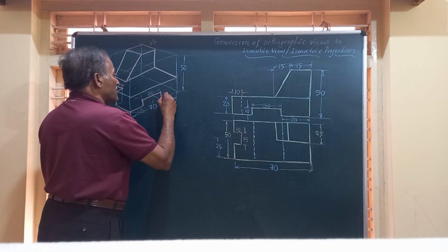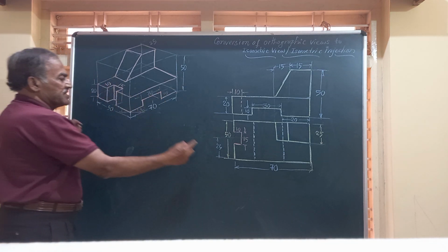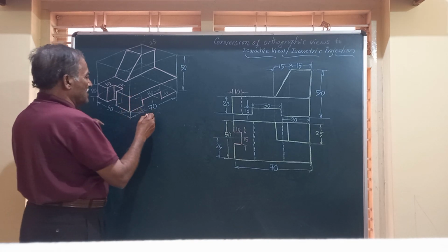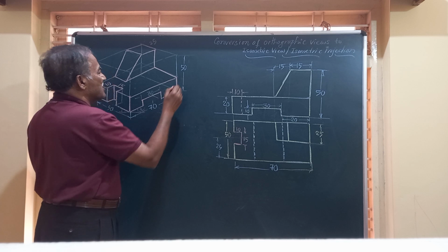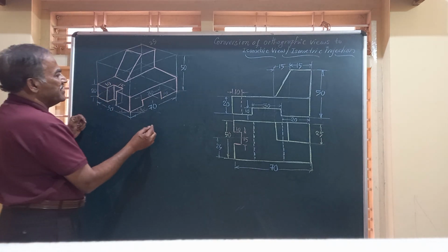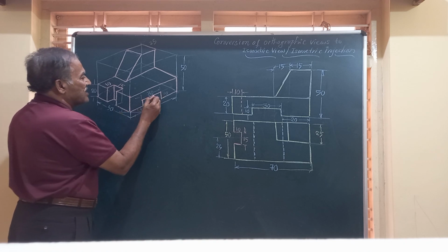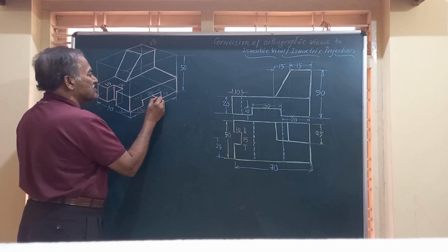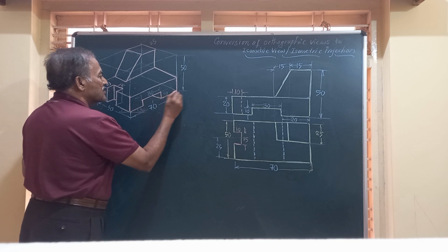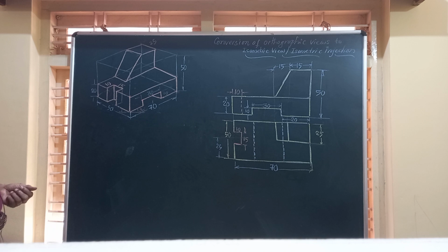that is cut along this face. Friends, this vertical edge I am going to show here. Again, this vertical edge from this corner. And friends, as you see, we have completed everything. But since this is a slot, I should write a line parallel to this through this. So this indicates that there is a slot cut throughout the 50 millimeter side depth.